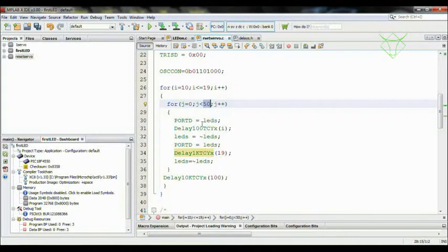Whatever positive pulse you have generated here, to set to that position you have to send at least 20 cycles of this pulse. That is what it says, but 50 is what is recommended. 50 means 1 second. You are sending the pulse for 1 second, so it will be set to that particular angle. Now I'm waiting for 1 second. This is a test code, so that I'll know the servo is sweeping.